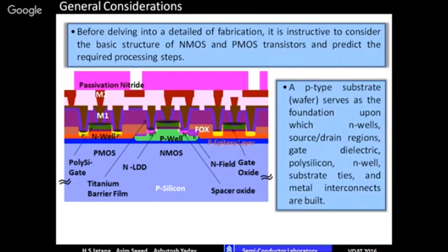After the end of the fabrication, this is the cross section which you are seeing. This is a P silicon, this is a P well, this is an N well. So let's take this N well. This is a P well. So these are N diffusion. This one is N diffusion. This is N diffusion. This is contact. This brownish is contact, and this blue color is a salicide to improve the resistivity.